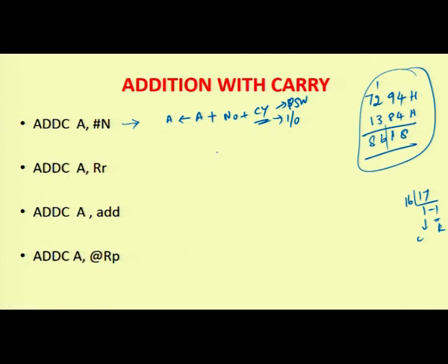You have to initialize the values, right. I will give the simple structure. First I will initialize the lower bit addition. Lower bit addition means MOV A, #94H. Then I will do the direct addition, ADD A, the next data which is 84. Either you can store it in a register and call it, or I will give it as immediate addition.